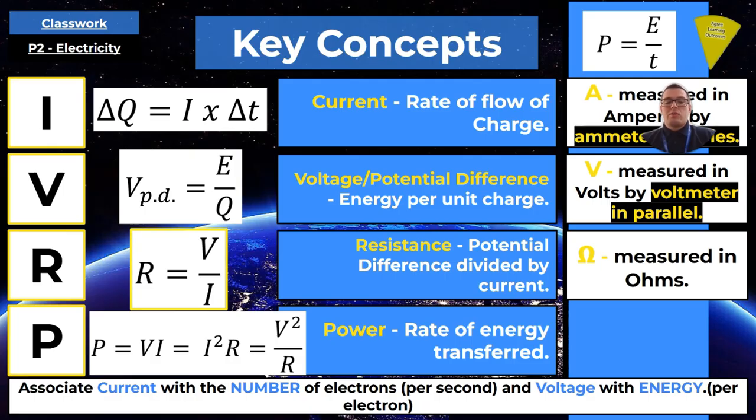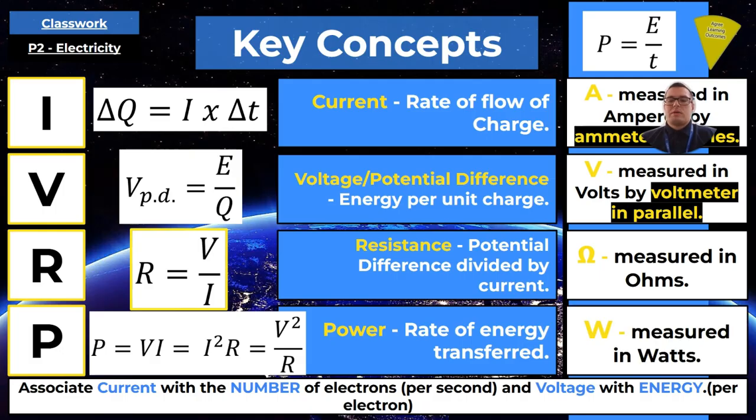The reason being, the 2 things that lead to energy being lost are current and resistance, because both of those 2 things will increase effectively the number of electron-ion collisions and therefore increase the impedance of electrons. So they will result in power being wasted when those 2 quantities are increased. So understanding that current is kind of doubly responsible there is, again, key to this relationship between current and resistance, which we'll talk about several times.